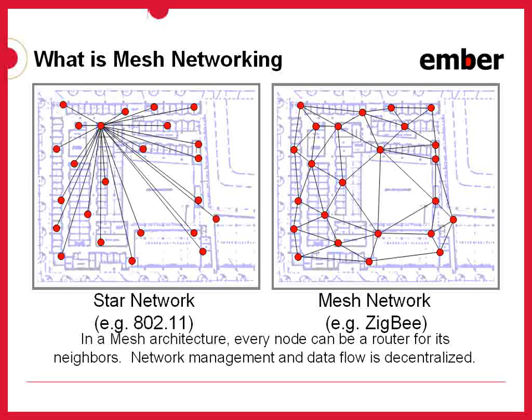Note that unlike the kind of repeater or range extender access points found in Wi-Fi networks, these intermediate nodes in the ZigBee mesh network can be sources or destinations themselves when it comes to application layer communication, maximizing their effectiveness and reducing the need for unnecessary devices. By leveraging a mesh network topology, ZigBee networks maximize effective communication range. They reduce the cost of the total solution by not requiring specialized repeaters or central access points, and they improve the reliability and robustness of the communications.